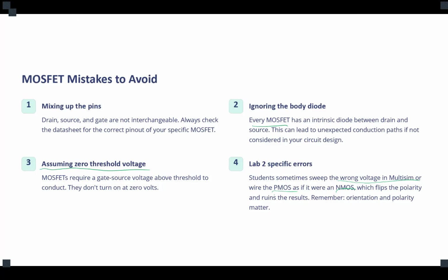So if you connect the wrong polarity based on the direction of the current, your MOSFET would not work right. Actually, wouldn't work. Is that clear what I mean? The direction of the current between PMOS and NMOS changes, and the current always goes from high potential to low potential. That's basic physics of current and voltage. So when you want to connect PMOS and NMOS, be aware of the direction of the current and the polarity of the voltage across the drain and source.